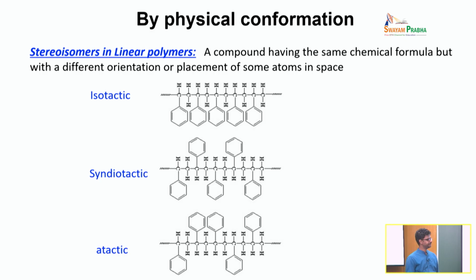You will write polystyrene polymer chemically the same, but if you look at the distribution of side group atoms, you see there is a difference, and this difference manifests in the physical and chemical properties too: the way they can pack, the crystallinity, the temperature resistance, and many other mechanical and electrical properties can be very much dependent on the isomer.